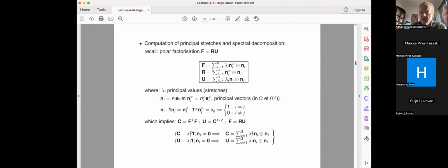And then basically, you can take the rotation tensor to have this n_i^φ times n_i tensor product, sum of these three, and basically with the eigenvalues equal to 1 because there's no change of deformation. So the stretch for the rotation is equal to 1. There's no stretch. The initial length is preserved to the deformed length, and that's what you got. The only thing is with the R, this is your two-point tensor, so it has this n_i^φ.